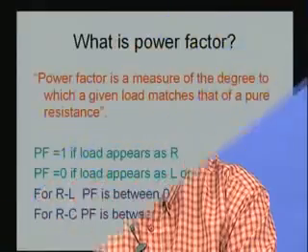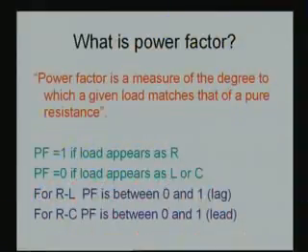In fact, if the load appears just resistive, then we say power factor Pf is equal to 1. And if the load appears purely inductive or purely capacitive, then that is most away from the pure resistive case, where the Pf is equal to 0.